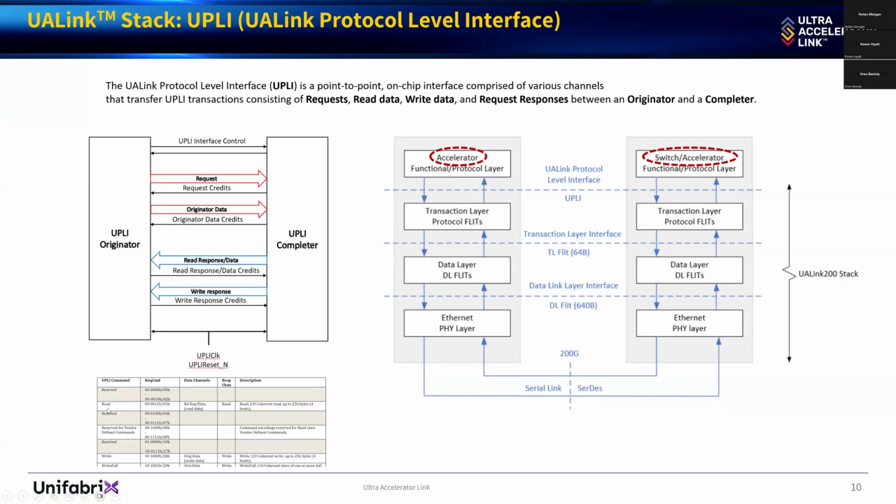You would see here, for example, a read command that uses the read response data channel to get the data back. And you would see a write command that can write up to 256 bytes. And it's using the originator data to pass the write data from the UPLI originator to the UPLI completer. And there are other commands. Some of the commands are vendor defined, so UALink allows a lot of innovation. If someone needs to define new commands, this is already built into the UALink framework, very easy to add. And UALink itself provides quite a comprehensive set of commands to use.